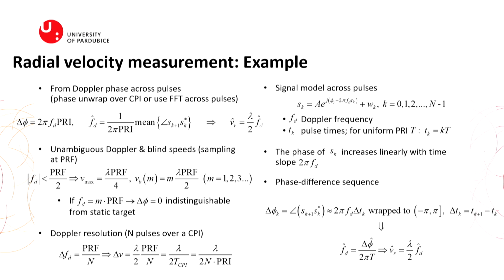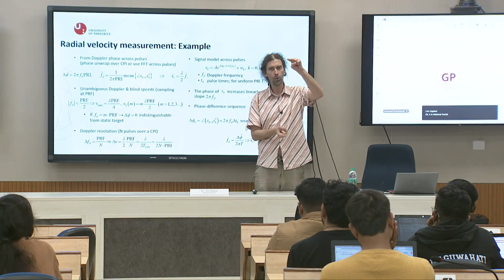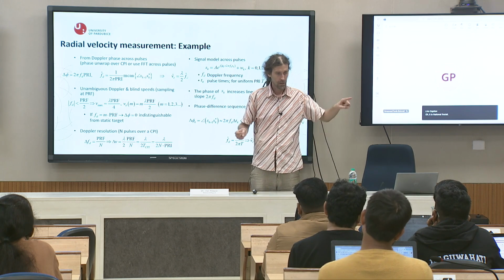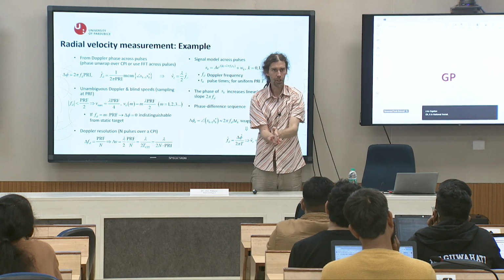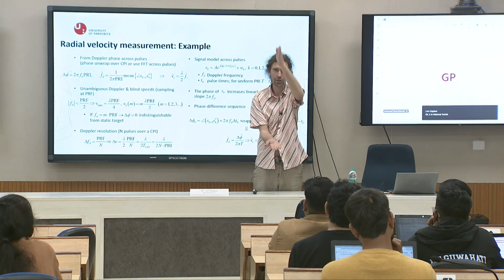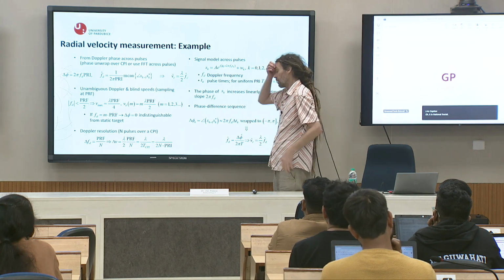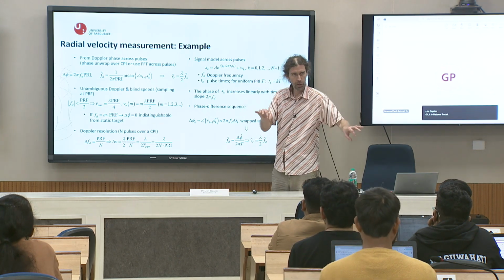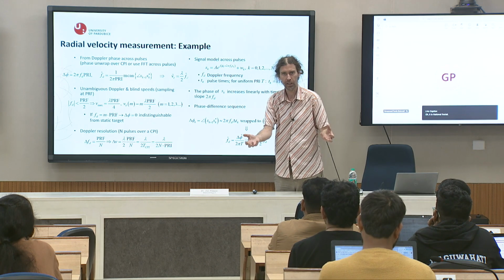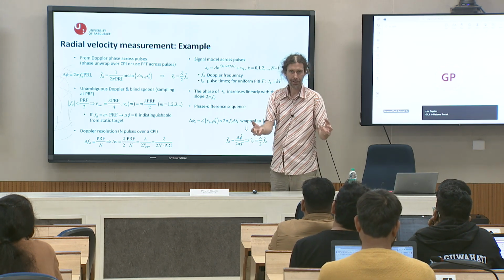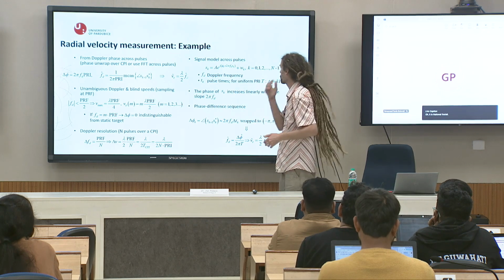If it is not linear, then something is wrong and there is some blind speed, or you are outside of control. Or you can do it from FFT. If you do it from the spectrum, we are looking for the maximum amplitude in the spectrum. That will be your Doppler shift, and Doppler shift is speed, almost the same. So there are two approaches. My scripts use both approaches, so you will see computation from phase or from FFT. They produce slightly different results because they are different approaches, so we will see.